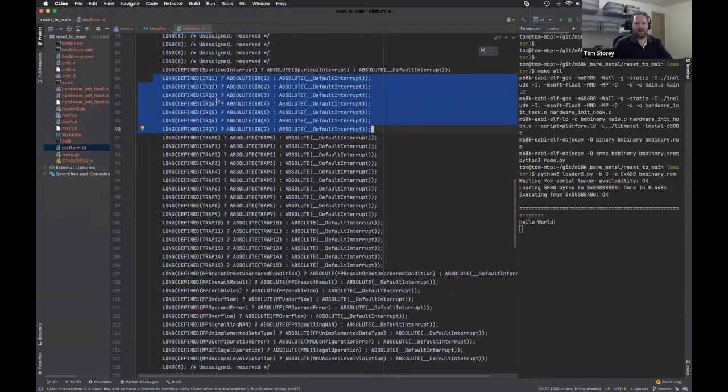So anything that's auto-vectored, you don't really have a choice about branching directly to some specific ISR. You would branch into one handler for that IRQ level. And then in that IRQ handler, the ISR, you need to go and test all the different potential peripherals that can generate an interrupt at that level and figure out which one has actually done it.